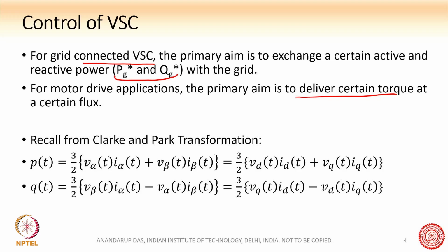However, the philosophy and understanding of what we are doing in this course can easily be replicated for a motor control application as well. One who understands grid connected converters and their vector control will also understand motor control, for example vector control or field oriented control of a motor, in a very similar and easy fashion.